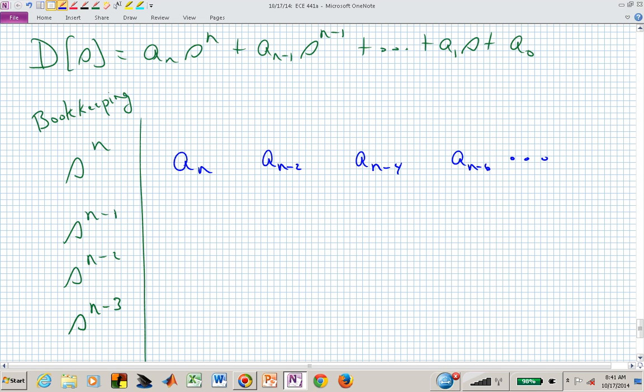Right, so if you have a 0 coefficient, it doesn't pass the Hurwitz test, but like I said before, I may not let you escape that easily on the test or homework. I may have you say, okay, so it's not stable. Tell me about the polynomial. How many roots are in the right half plane, how many are on the imaginary axis, and how many are on the left half plane? Because I want you to build the Routh array. Yes, so if you're just asking for stability and you have a 0 coefficient, you could say, it's not stable, I need to do something.